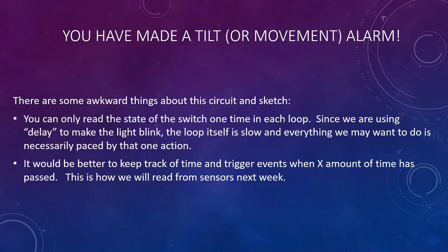There are a couple of awkward things about the way we did that, though. One of the major drawbacks of the code that we just looked at was that the entire void loop is being paced by the timing of the blinking light. So in order to make the light blink, we're basically telling the entire Arduino, go to sleep for 100 milliseconds, and then do something else, and go to sleep for another 200 milliseconds.